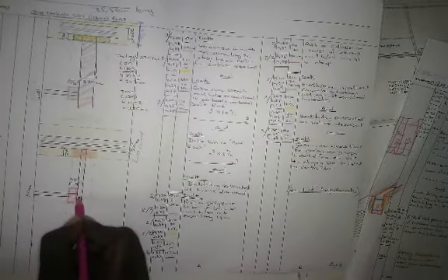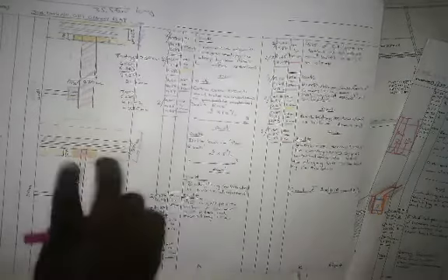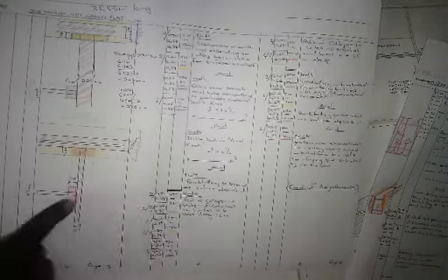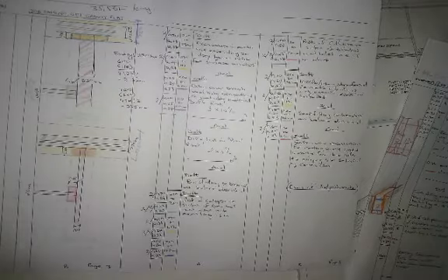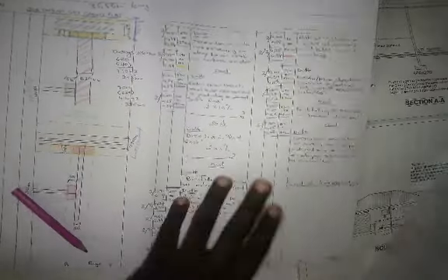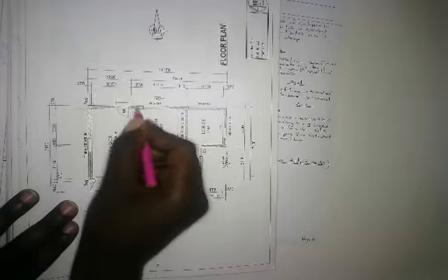You cannot re-excavate this part, but this one has not been excavated. So you need to deduct this part because it's already been measured when you are excavating this one. Same thing that is happening over here, where your 110 comes to your 110 and makes a T. You've already excavated this part. You cannot excavate this piece again. You can only excavate from here to here, okay.